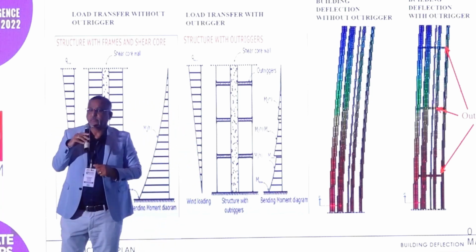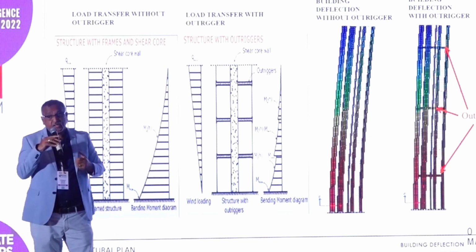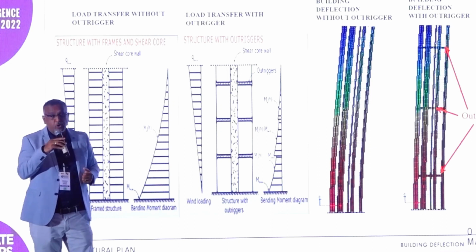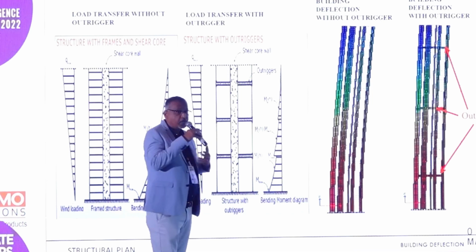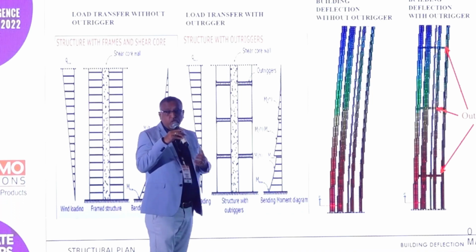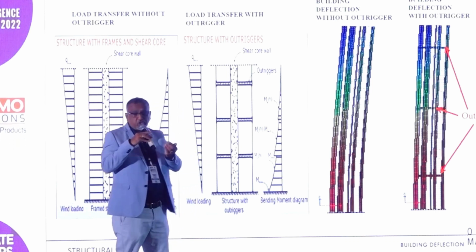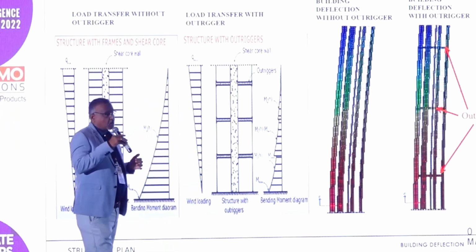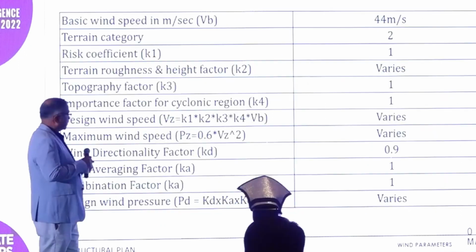And not only the deformations are important, comfort level accelerations under wind loading are also important. I mean, whatever accelerations are developed under extreme wind conditions, they should not disturb the residents. They should be within the limit of perception, and the comfort criteria should not be disturbed.